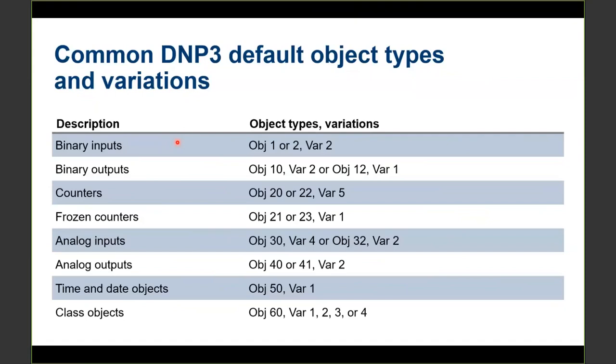This is a very interesting feature to be applied, especially in RTU applications. So, for example, when we have one RTU polling 25 relays and providing a DNP map to the SCADA system in just one map, when the RTU loses communication with one of the relays, the RTU will change the status of the DNP index associated with that relay that lost communication.